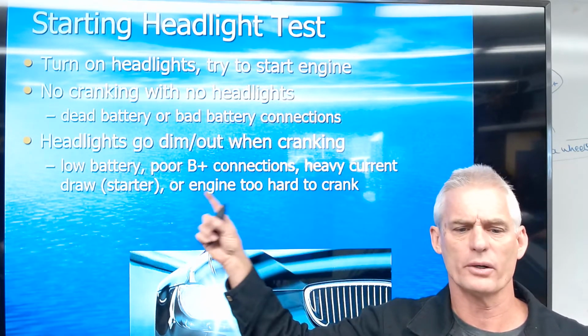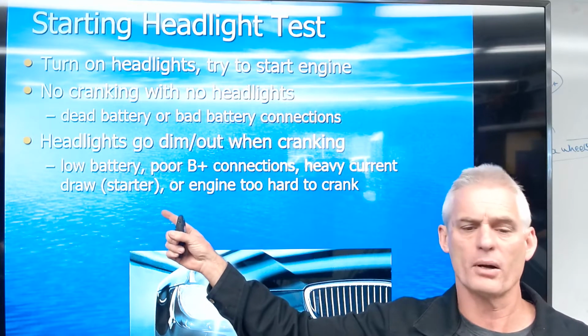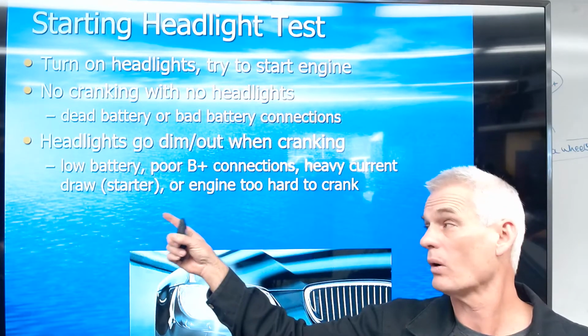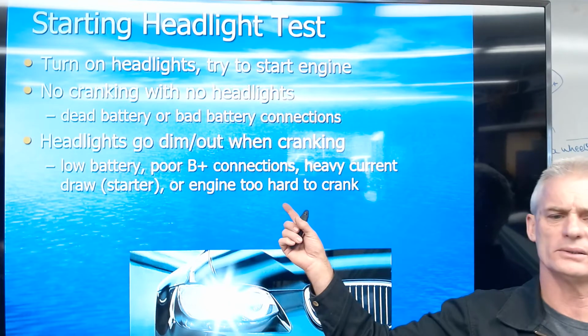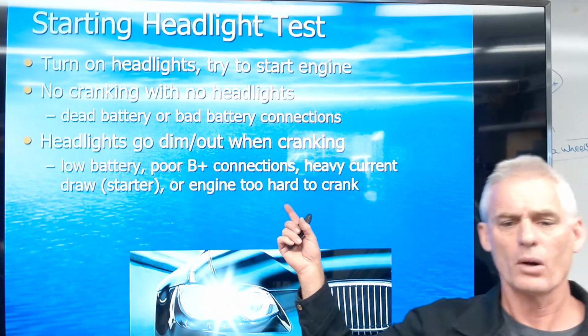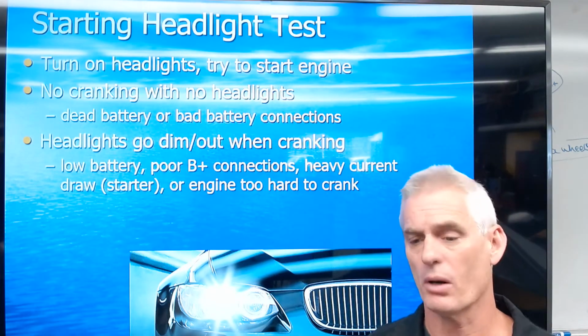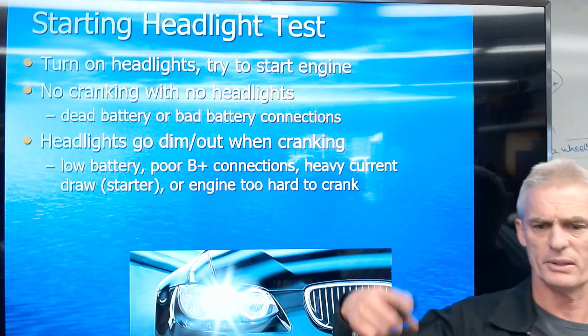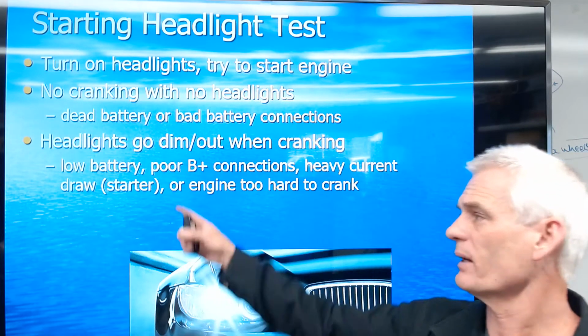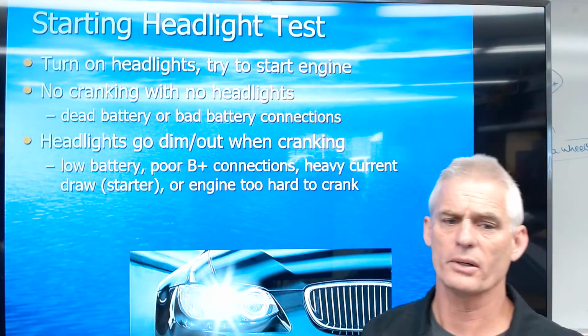We have heavy current draw, which can be a problem inside the starter, or the least likely cause is something mechanically wrong in the engine that's making the engine too hard to crank or to spin over. But usually we've got a battery with a low state of charge.